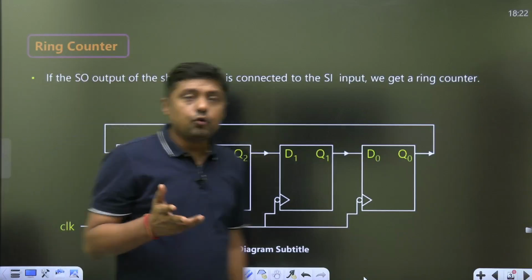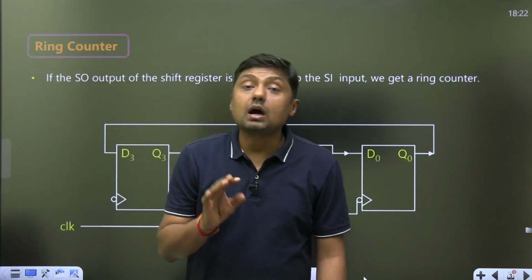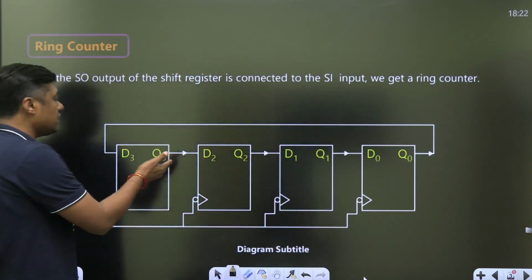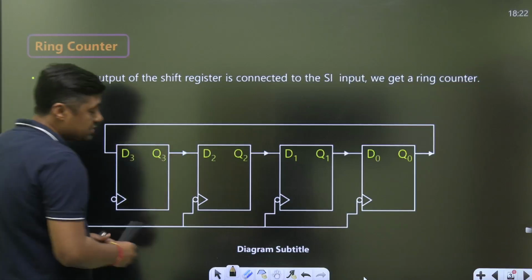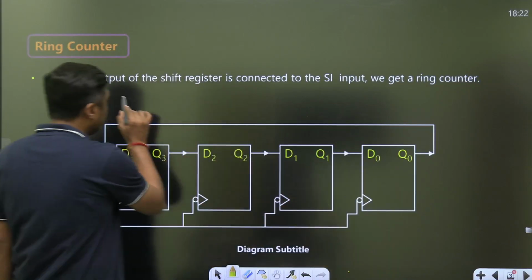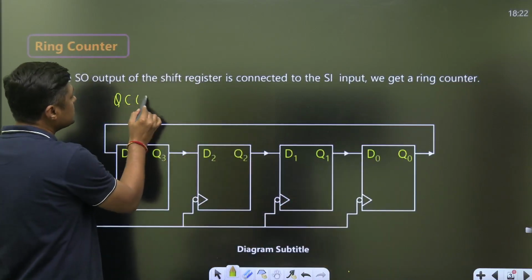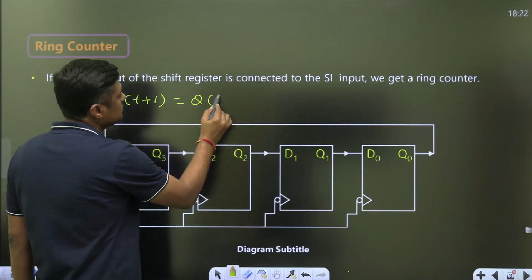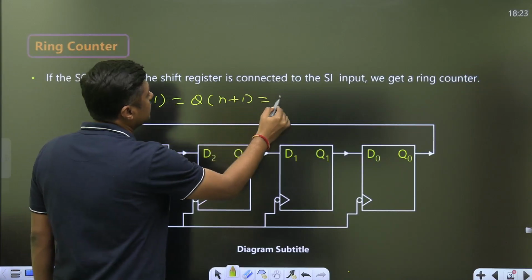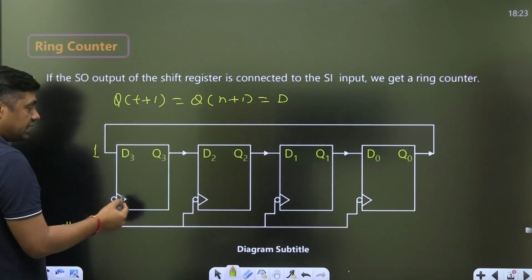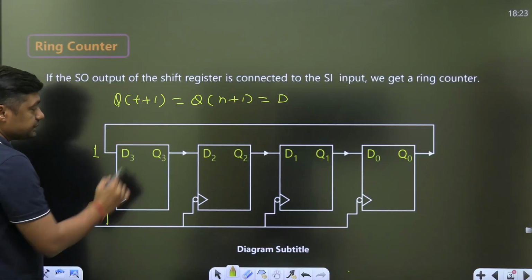What is the D flip flop? That is called a transparent flip flop. The next state for D flip flop, Q(t+1), or sometimes known as Qn+1, will become D. For example, if D is 1, then when we give the timing signal, it will become 1.